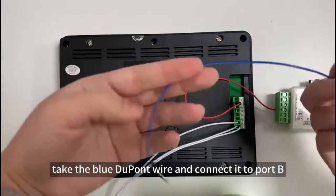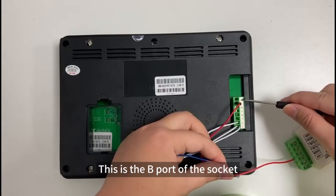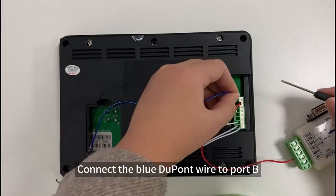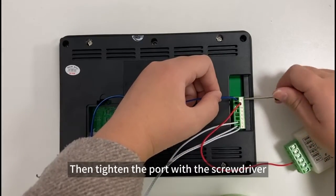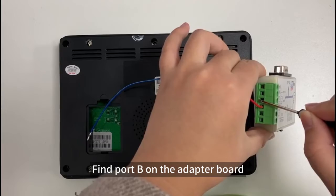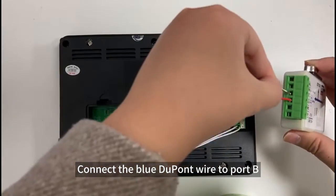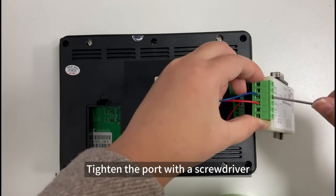Next, take the blue DuPont wire and connect it to port B. This is the B port of the socket. Connect the blue DuPont wire to port B. Then tighten the port with the screwdriver. Find port B on the adapter board. Connect the blue DuPont wire to port B. Tighten the port with a screwdriver.